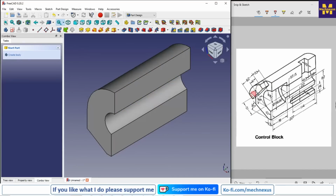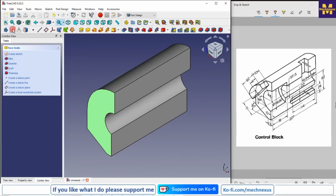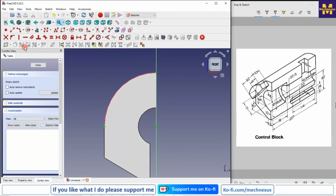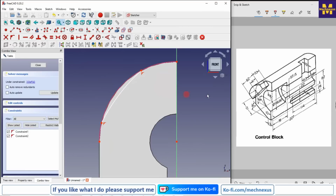And now we will make this boss. I will select this face and say sketch, and I will project my outer edge and create a 3-point arc, and I will select this one and my arc and say equal, and we can say that here the angle is 38.